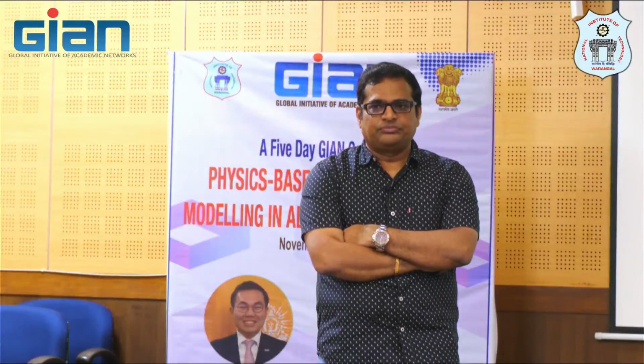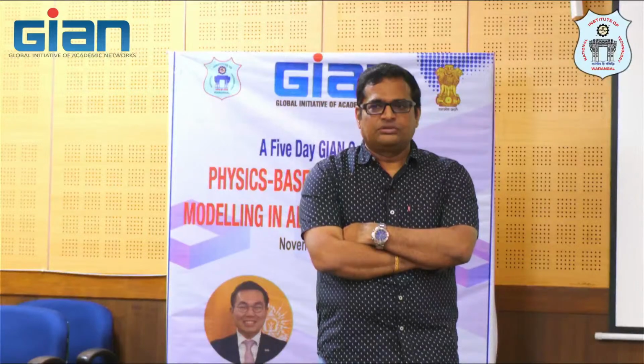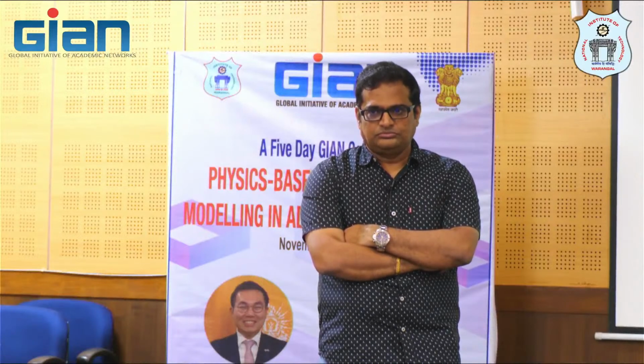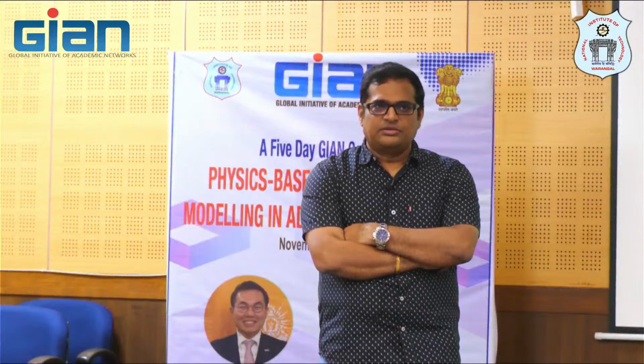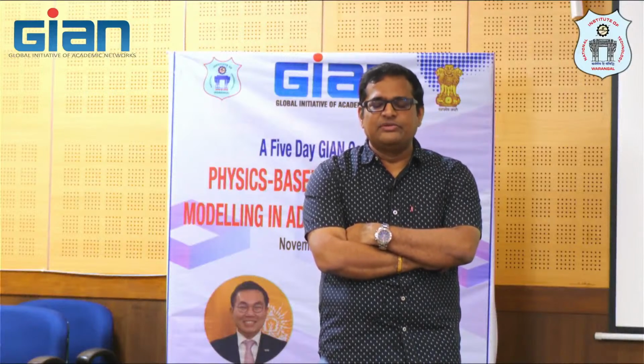Generally, the important aspect of this design is to create the defect structure in the bone, whether it is maxillofacial or an acetabular cup where the bone is defective. There is some defect because of the cancerous cells and all. So the defect region has to be captured and redesigned, and the positive part or the negative part of that defect structure has to be incorporated. If it is a symmetric defect, then we will mirror it. But if it is asymmetric, we need to do it right from scratch. If it is symmetric, it will be mirrored and redesigned. Mostly what we see is an asymmetric structure only, which has to be incorporated into the implant.